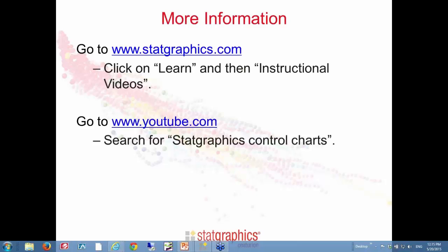When you have a dynamic process, for example, as we had with that concentration, there is some correlation between observations 1 minute apart, 10 minutes apart, 20 minutes apart. But once the observations get far enough apart, let's say 8 hours apart, that correlation has totally disappeared. If I talk about long term, I'm talking about a long enough period that the correlation between the observations at either end of that period has dissipated, is gone.